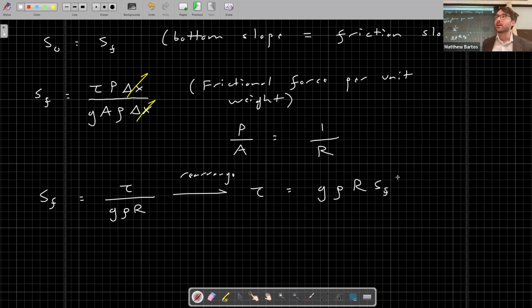So if you remember back to when we first started looking at equations for frictional losses, we derived the Darcy-Weisbach equation by taking this expression for the mean shear stress and equating it to another expression for the mean shear stress given by Newton's drag law. So let's go ahead and do that again. From Newton's drag law, we have that the mean shear stress is equal to some drag coefficient C_F times the density of the fluid times U squared over 2.